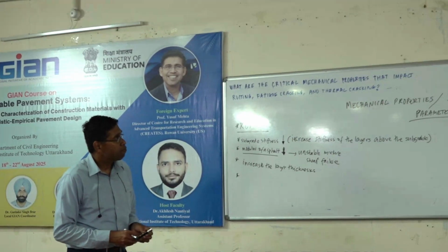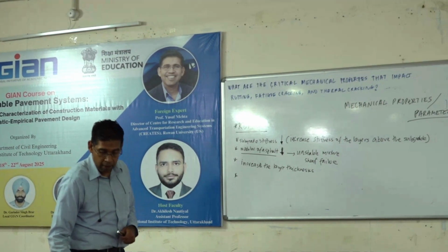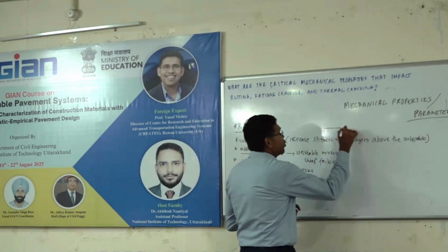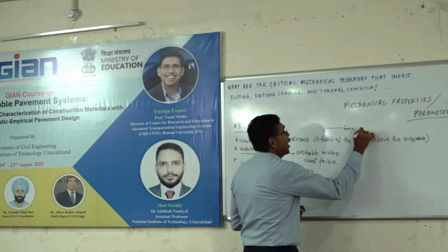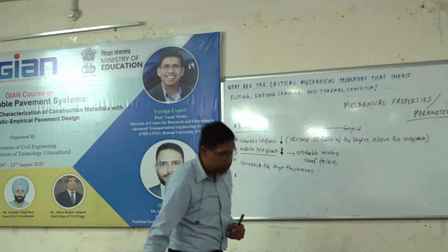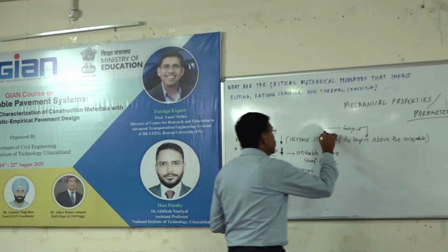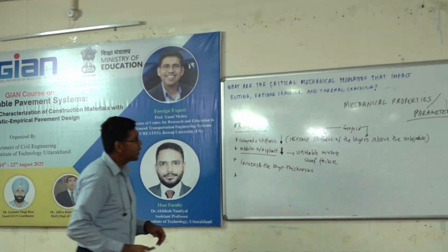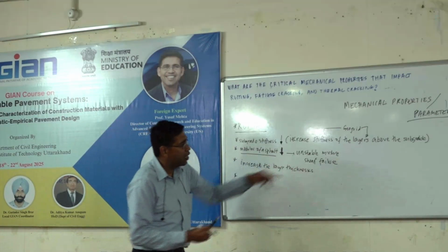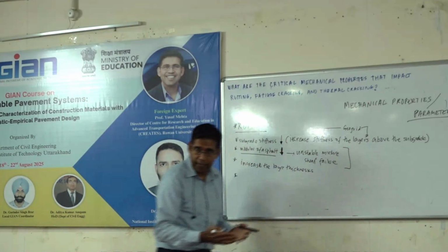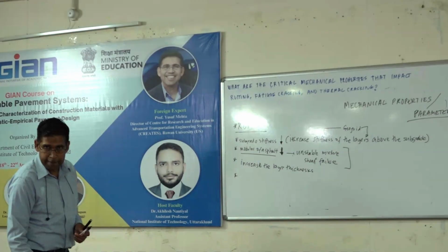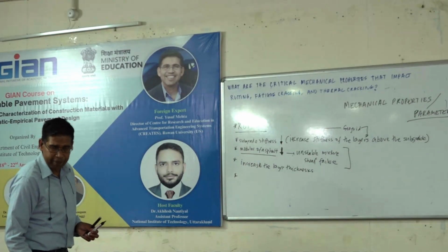What causes rutting? This is very good. Can use geogrid. Geogrid, yes, you can use geogrid because that's right. So you can use geogrid right here to kind of stabilize the layers above that. Okay, what else? That's good. Anything else on rutting? Modulus of asphalt, unstable, makes a shear failure. You make your aggregate stronger, right? I talked about binder, and so on and so forth. What else? Anything else comes to mind with rutting?